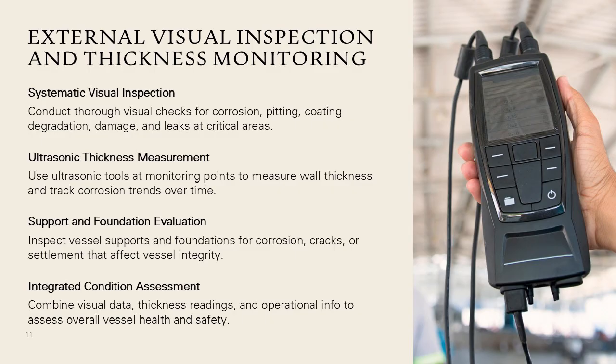Ultrasonic thickness measurement is a key quantitative tool used during on-stream inspection. Measurements should be taken at established corrosion monitoring locations to ensure consistency and allow meaningful trend analysis. Data should be compared against minimum required thickness values to assess remaining corrosion allowance and estimate remaining life.